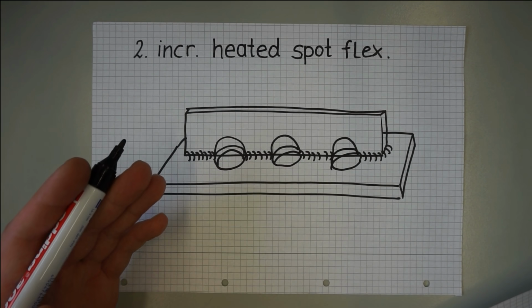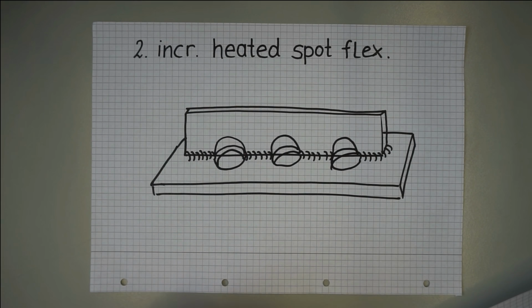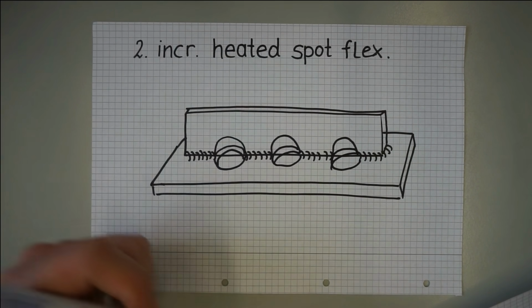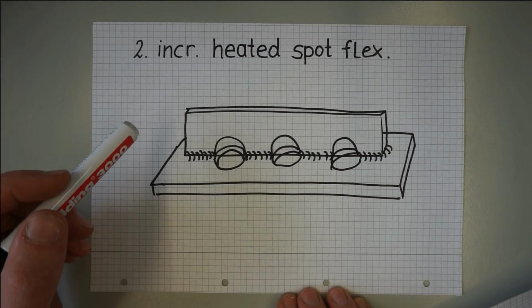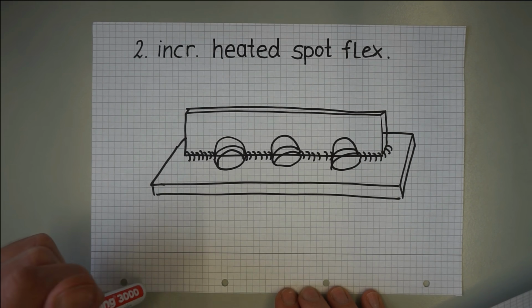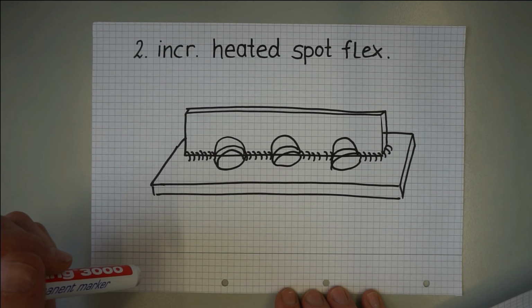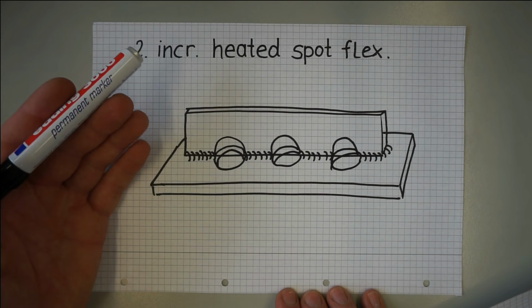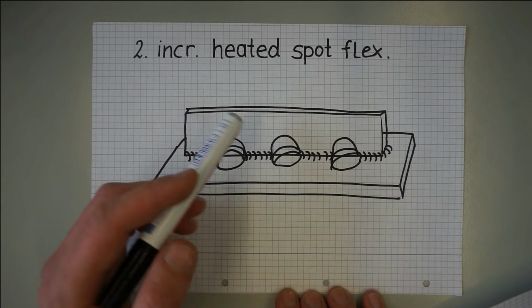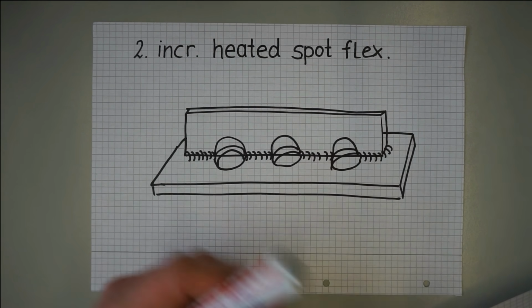Also, there are joint types which are less constraining. For example, in this regard, corner joints are better than butt joints. Also, the location of the weld bead in the workpiece can be smart or not so smart in terms of constraining.